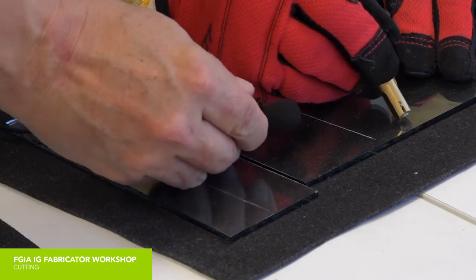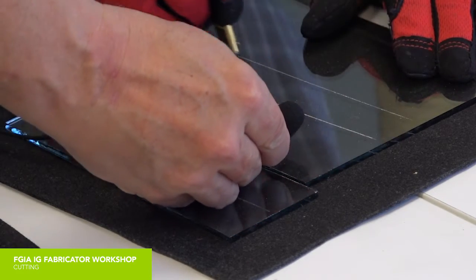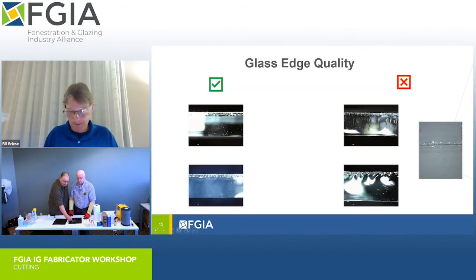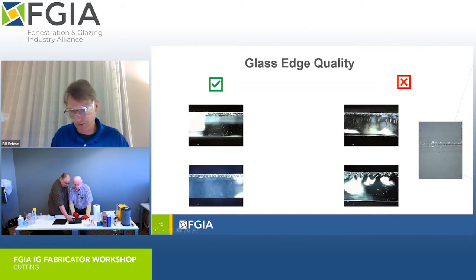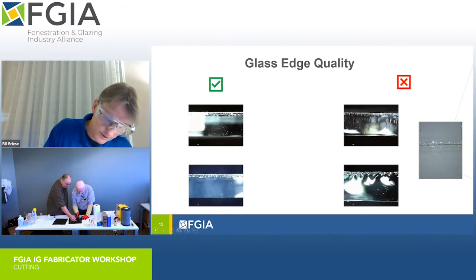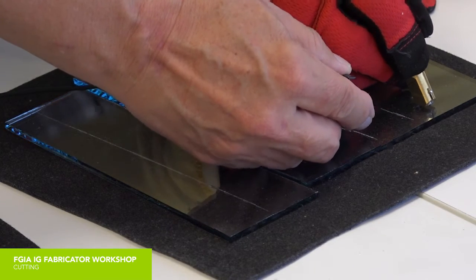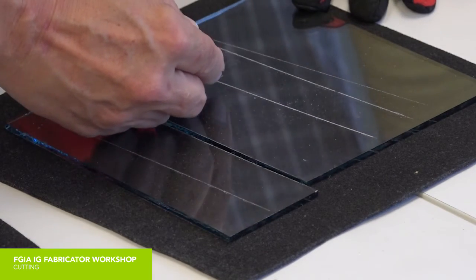Ooh, this is really interesting. I'm getting, and it's hard to see here, a lot of slivers. It's actually popping. So I've done one of two things. I've either got too strong or too sharp of an angle, or I was pushing down too hard. So I'm going to try pushing a little less. Much better.